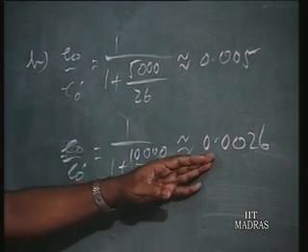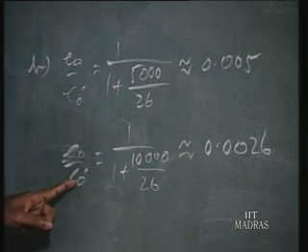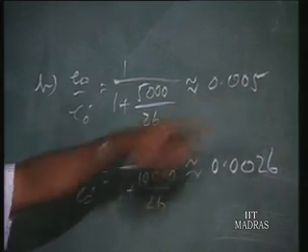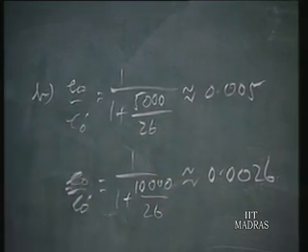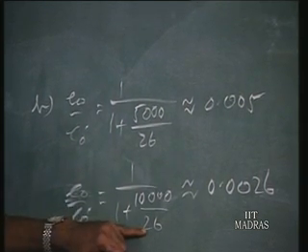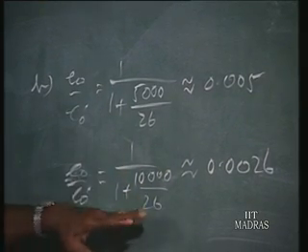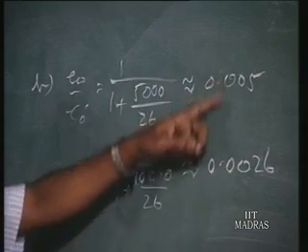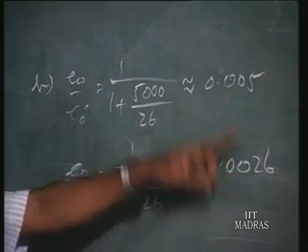So this also, if it is 0.2%, that is for 100 volt theoretical voltage, the voltage output will be only 0.2 volt. Previously it was 0.5 volt for 100 volt theoretical value. It is 0.2, still much reduced. So you find when the input resistance of the instrument is very, very small compared to the output resistance, the loading effect is enormous, and not only enormous, it is varying with wide limits. The 0.05 is around nearly twice this value.